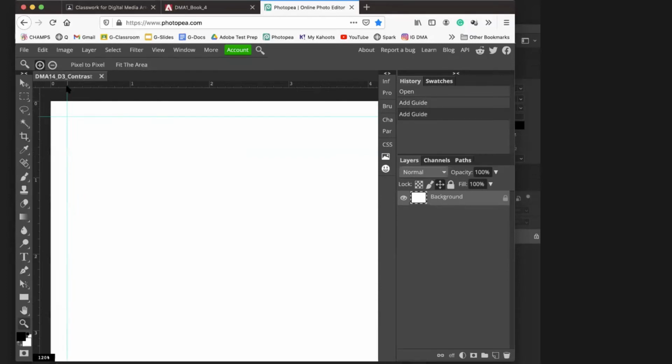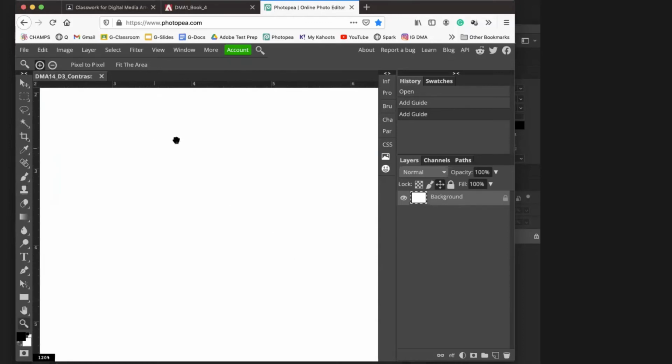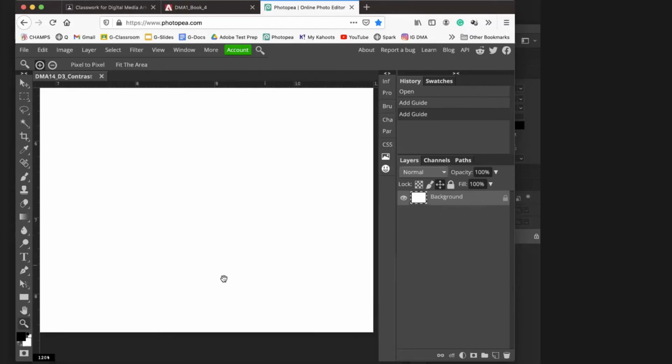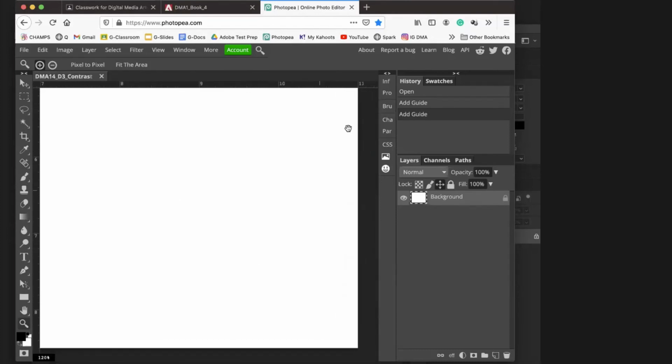There's 2 little lines there. I don't know if you can see them, but on yours, you will be able to. I'm zoomed in about 120%. So we just added those 2 lines in the rulers. You click, hold, and drag from the ruler out. Now I'm going to hold the space bar to get the hand, and then I'm just dragging to see the bottom corner. All right. So now I'm going to do the same thing. I'm going to drag a ruler to 2 of the lines there. So you click, hold, and drag from the ruler. That's where you get guides.